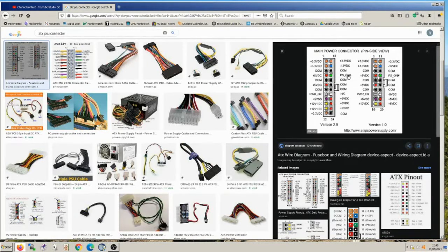You see that's got PS underscore on, power supply on, and a little hash, yeah? When you see that little hash, it means that has to be connected to 0 volts ground to activate the power supply. So power supply on hash means it's active when it's low, yeah? It's active when it's 0 volts, and that's got about 5 volts on, okay? And purple one, 5 volt standby. So what I've got on this board is I've got 5 volt standby going in.